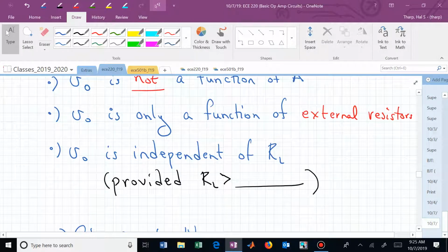So that puts a constraint on the size of that load, the size of the resistor that we can hang on to the output pin. If we're demanding more current flowing than 40 milliamps, we're not going to get it, and so the voltage is going to actually be less than what we expected. It just can't quite supply that much current.